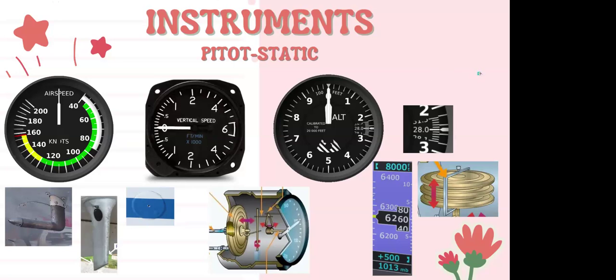So the airspeed indicator gets information from both our pitot tube and our static port. What does it do with that information? What does that information do for us? Well, when we are moving through the air, right? Like we are an aircraft moving through the air. That's called dynamic air. That is the airspeed that we are picking up by being a moving object through the air. So essentially the same as your speedometer in your car, right? Your car is moving through the air. That's the speed we're measuring.